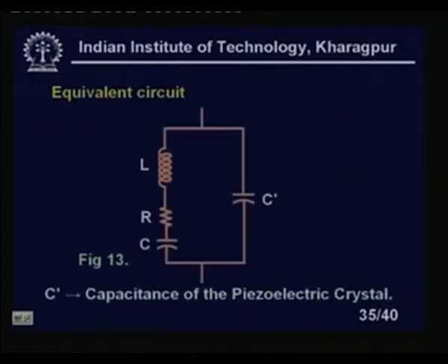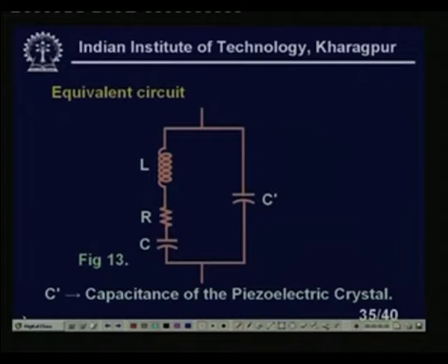I have an inductance L, a resistance R, a capacitance C, and also a parallel capacitance C dash. This value of L is very high in the case of piezoelectric crystals. That makes the frequency stability excellent. Otherwise, nobody should care for these quartz crystals, right.